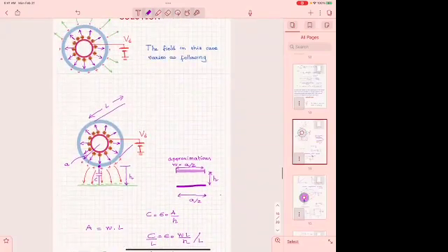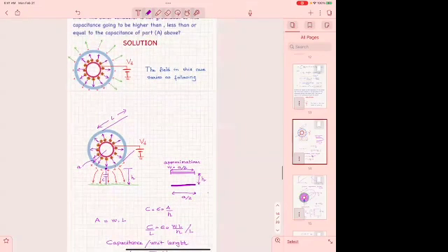A lot of times, in all of my experience, when my graduate students go into the lab to make a measurement, the measurements don't look anywhere near what they are supposed to be. Most of the time, it's not their design, it's the grounding. They don't have a good ground in the experimental setup. So, any questions about this?